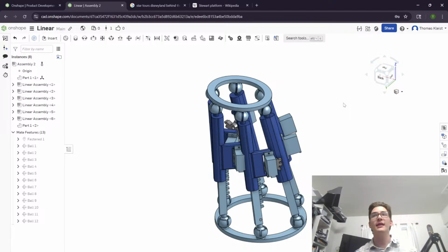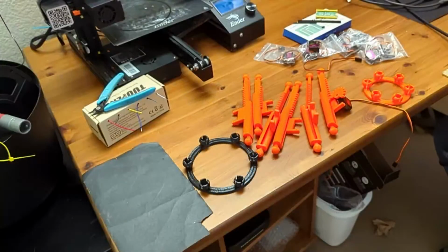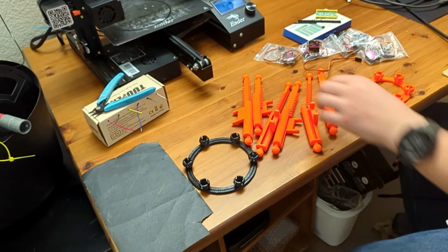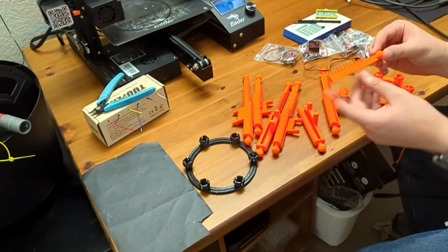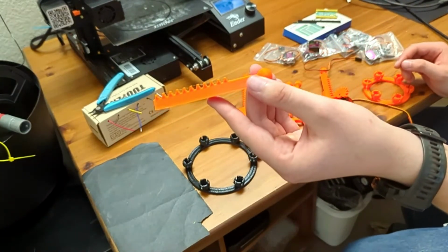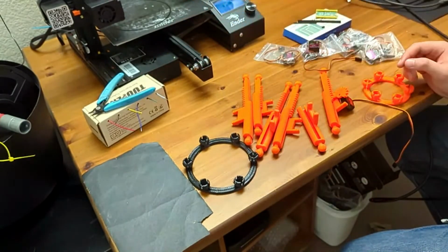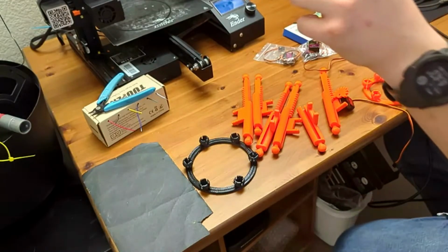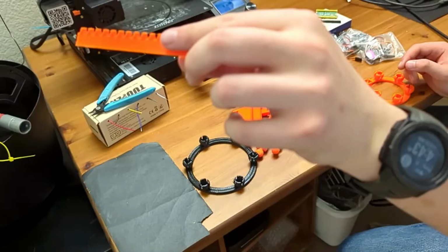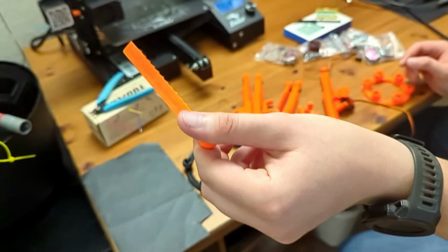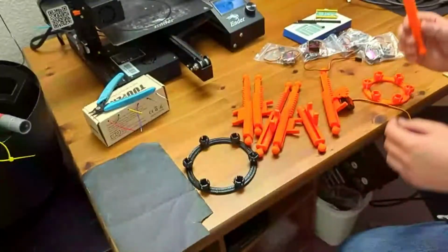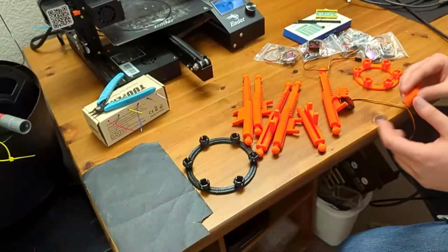With all that being said, I think we should probably start working on the actual assembly here. One thing about it is I printed these with ASA, which I don't really like all that much. My Ender 3 really can't handle it, even with an enclosure I built out of cardboard. So they're pretty warpy and not the most dimensionally accurate parts I've ever made. There is going to be a little bit of sanding involved to make it slide nicely in the holder.